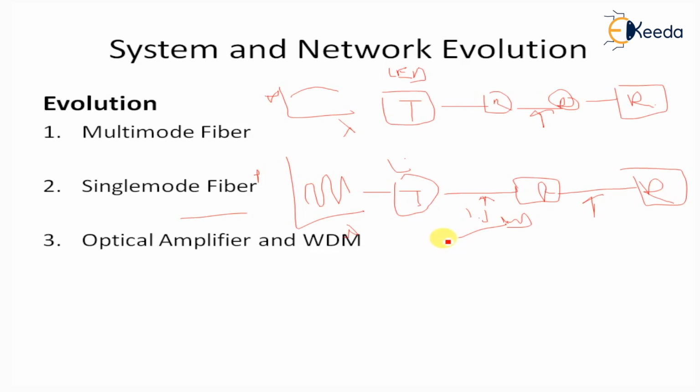Using an external modulator along with the DFB, distributed feedback laser, and EDFA allowed systems to achieve a distance of about 600 km at approximately 2.5 Gbps between regenerators over standard single mode fiber. The next invention was the chromatic dispersion compensating technique, which is used to compensate for the dispersion introduced by the fiber in the optical network.